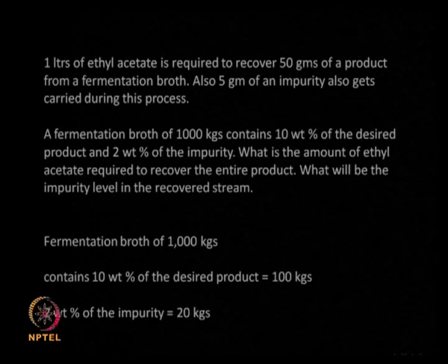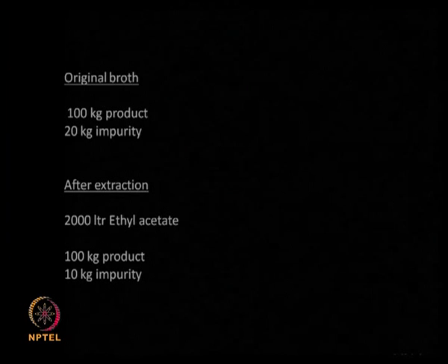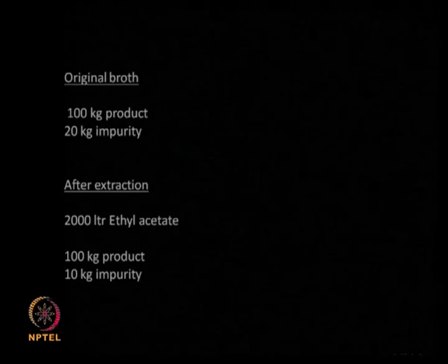So extraction is a good method, but if this impurity solubility is higher, then you will get a lot of impurity also taken in with the product, and then we may have to go to some other way of purifying the product and removing the impurity from the product. So it is not that extraction is the only way of purifying the product, we may have to try different techniques and different methods. Okay.